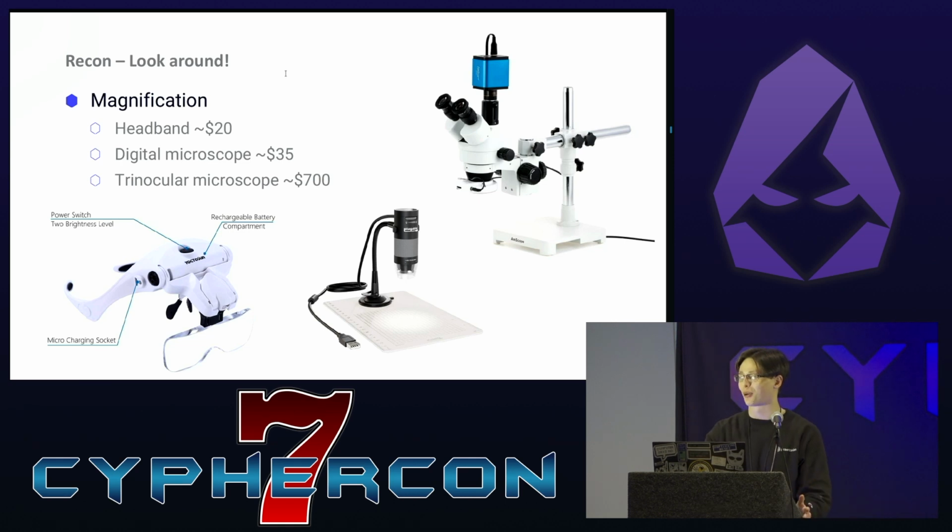And then I mentioned a little bit earlier, magnification. My eyesight is not great, and some of these components are small. So having some solutions for magnification can be really helpful. Over on the cheaper end, they have these magnifying headsets. I think these are actually pretty good for doing inspection after you've done a soldering job, but I find that if you're trying to solder while wearing them, it can be kind of awkward and they can get in the way.